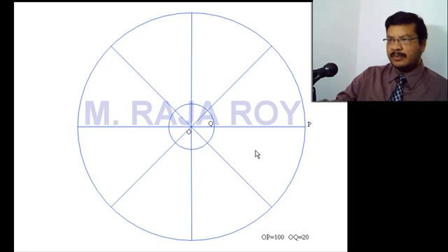Now I am going to draw the Archimedean spiral for 1 and 1/4 convolutions. That's why you give the numbering as for one convolution 8 parts, for another 1/4 convolution, that means up to here 1/4 of the circle you have to cover.